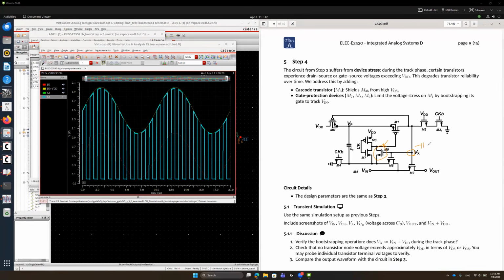That means added parasitic cap. And as we studied in the previous quiz and lecture slide, if there are more parasitic caps, then after charge sharing, or after applying the charge conservation law, the bootstrapped voltage will decrease because of that parasitic cap.